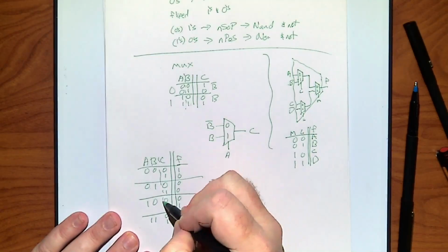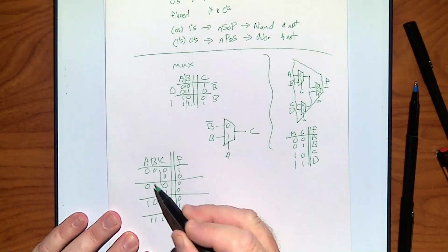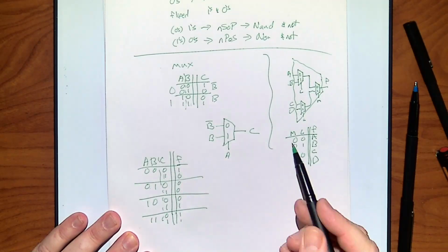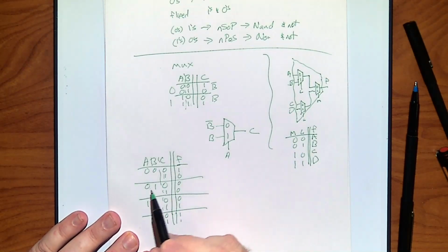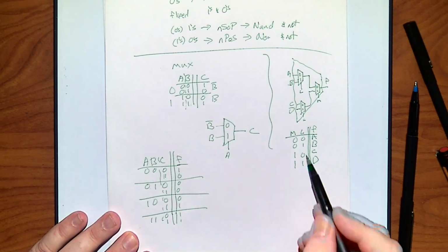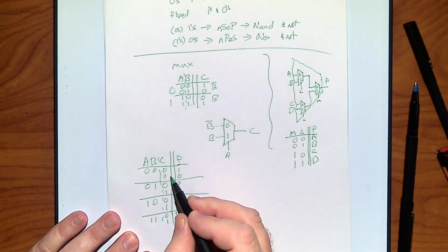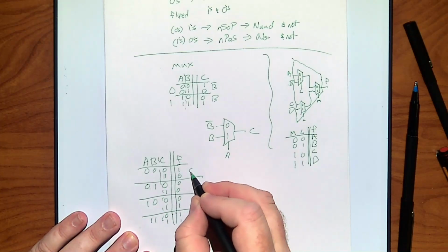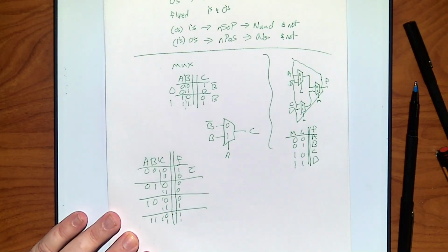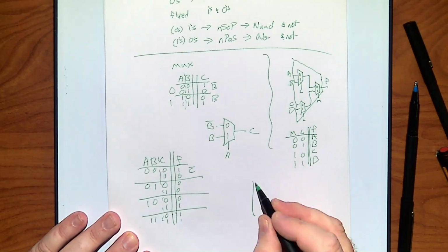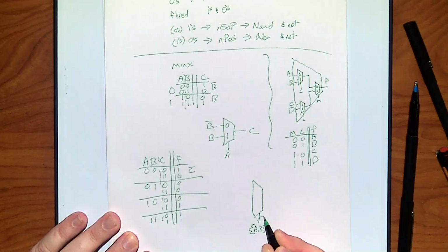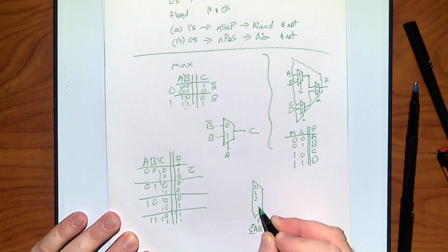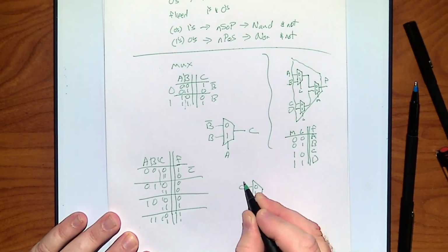So again, this is the one I'm going to hook to the inputs. This is my control AB, giving me my most and least significant bit. And then all I do is hook to the input. When the input is on 0, well, F is the opposite of C, so I'm going to hook C bar to it. So on my mux, I've got A, B together as my 2-wire controller. 0, 1, 2, 3. On 0, I hook C bar.